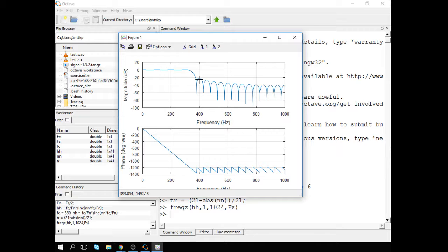Excellent. How to improve it more? Use a real window, not triangular. The only good part of the triangular window is that it's fast to calculate, even on a small processor. But on the other hand, you usually know the width of the window by selecting it, so even for small processors you can always have a constant lookup table for the coefficients.